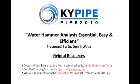Okay. Is it okay to use Pipe 2010 Surge for liquid hydrocarbon or crude oil? Well, yes. Part of the data is the viscosity of the fluid and the density of the fluid. So it is appropriate to use it for any liquid where you know those properties. It should be a liquid though.